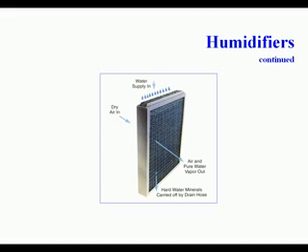In this chart here, this is a psychrometric chart. A to B indicates the air being heated. B to C shows the warm air passing over the humidifier. Between C and A, heated and dehumidified air is mixed. D indicates the final condition of the air delivered to this conditioned space. It requires about 100 BTUs to vaporize each pound of water.